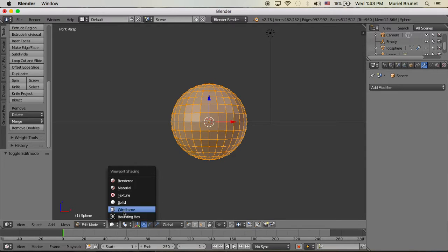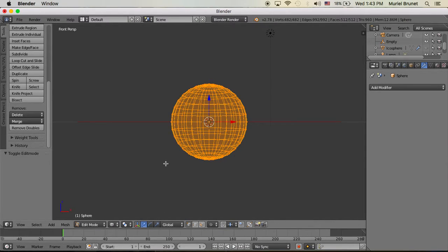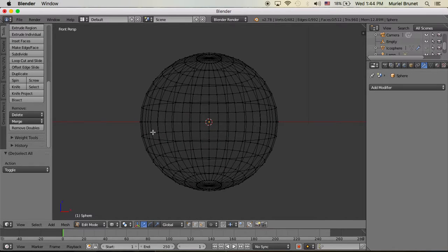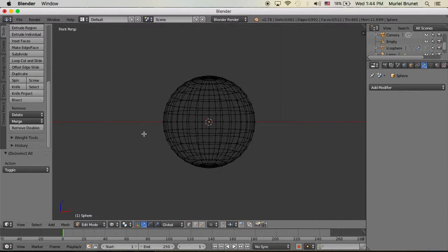and select wireframe to select the middle 3 vertices, or rows of vertices, in this sphere. So I'm going to click A to deselect, and then B, and I'm going to select the middle 3 rows. I suggest maybe zooming in here because it's a little hard to see.